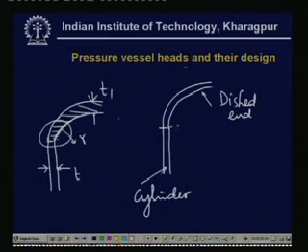Now, here as we have discussed, sigma m, here of course the longitudinal stress, and here again the sigma m, this changes continuously, but in case of sigma t it changes abruptly, that is, the sigma t here and sigma t there will have two different values. So, this is quite important, because then we will have to make adequate reinforcement, that is, here of course the tendency is that there will be a stress concentration.